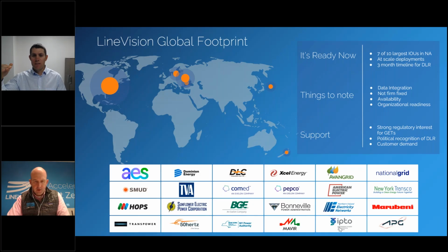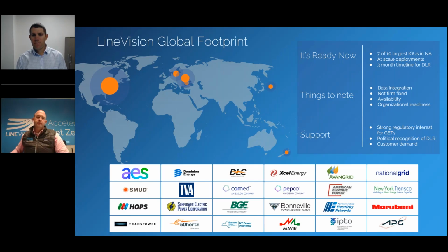It's really just, instead of an AAR rating, you're going to see a DLR rating that you're operating on for that line. And that's also what the RTOs, whether we operate in PJM and MISO, and what those regional transmission organizations will see as well, of what limits are passed along through the EMS. So yeah, I think there's definitely a component there that needs to be factored in the project, but especially when you think about 881 and the work already being done, it's not a huge lift there on the data integration and organizational training piece. I like that.